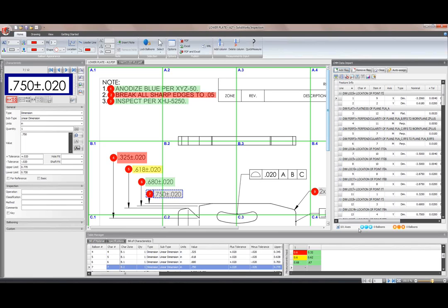Now, if when the CMM was set up, all the annotations and dimension numbers were relayed over to the CMM, then they would just match through exactly. That would be great, that would just work straight away. We could auto-assign all the item numbers and it would just work. Now, I don't know how often that's the case, so if that's not the case, we can do some other things. We can manually assign things, so say this is balloon 4, this is balloon 5, and go through manually. Of course, we'd rather not do that.